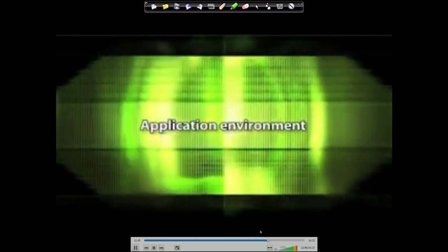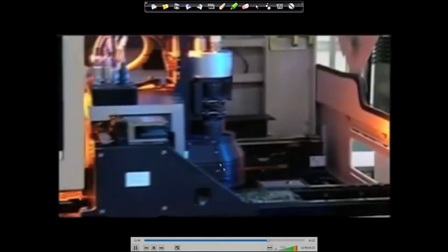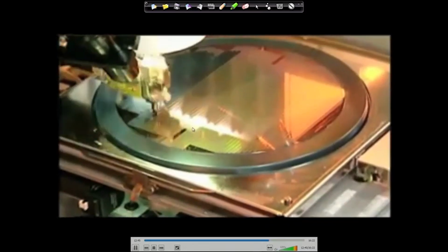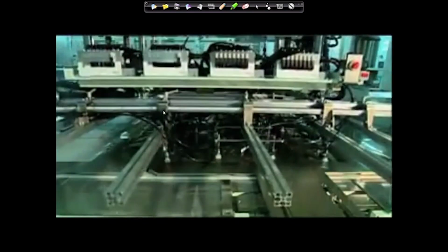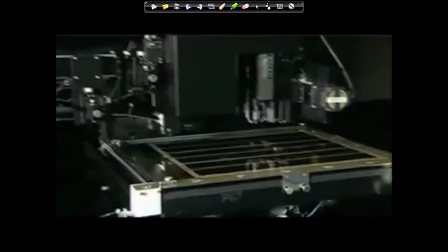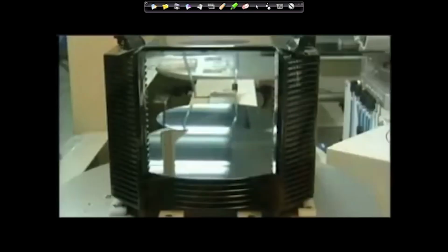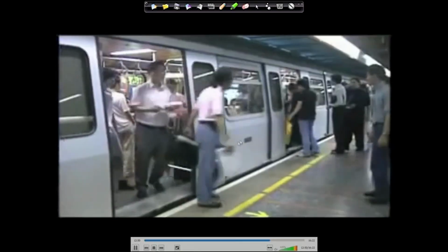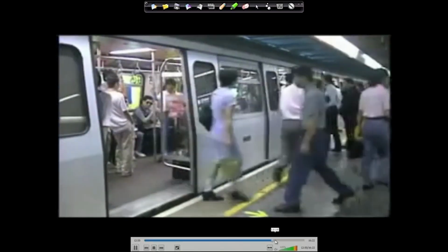So, these are the different things about the process. Now, where do we use this? We use it wherever we need very highly precise motion. Mostly it is for pick and place type of tasks, moving one component to another location, where a difference of a few microns also plays an important role. So, those are the applications of this particular linear guideway.